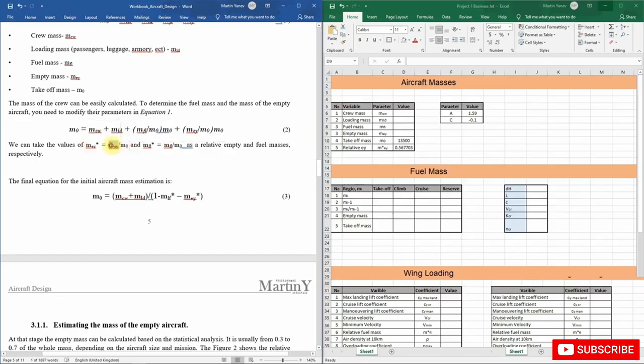So MEY, or the empty mass, will be equal to MEY star, or 0.56, multiplied by the takeoff mass, or 13,500. So this will be equal to 13,500 multiplied by the relative empty mass. I will press equal, and we get that the empty mass of our aircraft will be equal to 7,663.996 exactly.